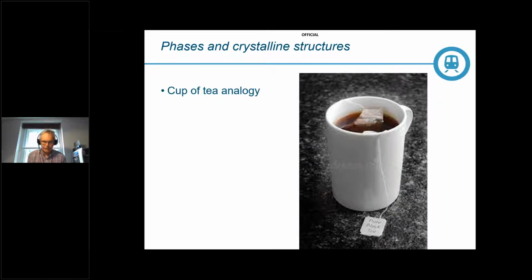On the other hand, the sugar will definitely start to crystallize out as the temperature falls. So water and tea in a solid state remain as one phase, but water and sugar revert again to two phases. And this system is analogous to the behavior of carbon and indeed other alloying elements when dissolved in molten metal.